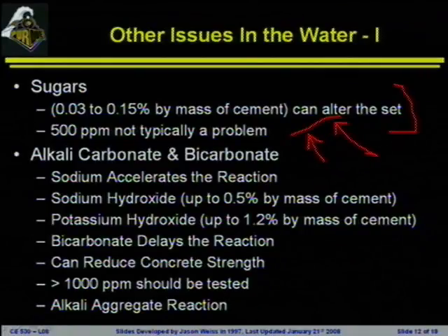You throw the sugar in, does it have to be in before final set or before initial set, or is it just before final? Typically they would be throwing it in before initial set, but usually, if you're mixing it, it gets mixed in, and it'll stop the process. Typically it's before initial set, because once you get toward initial set, it's pretty tough to be mixing it in, because you're getting something that's pretty stiff.